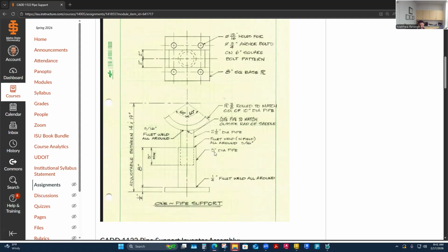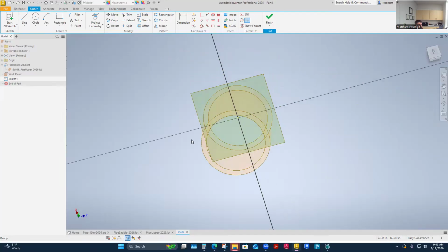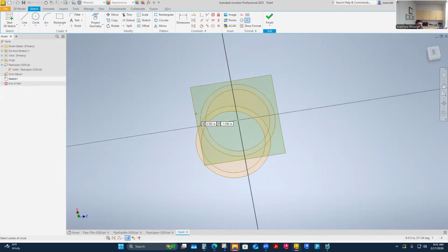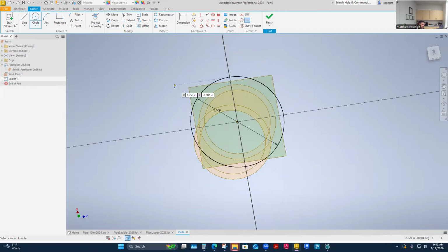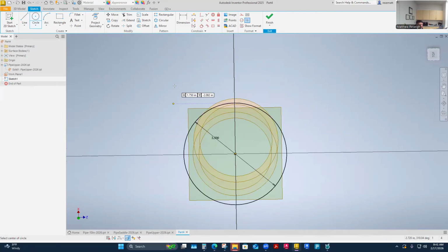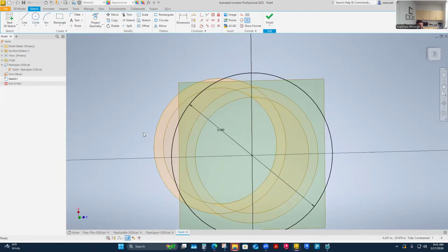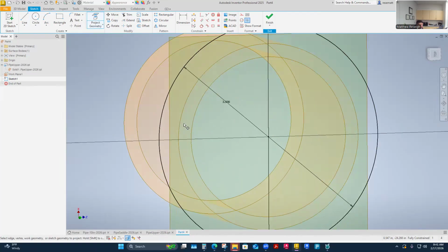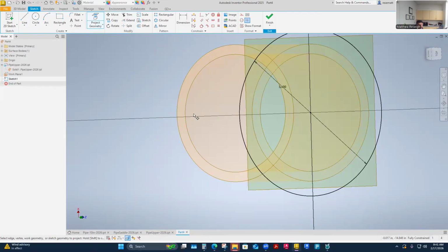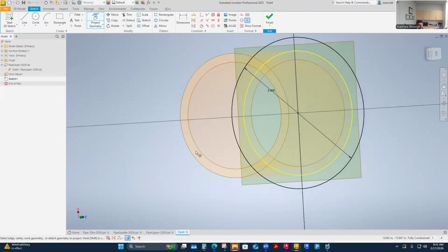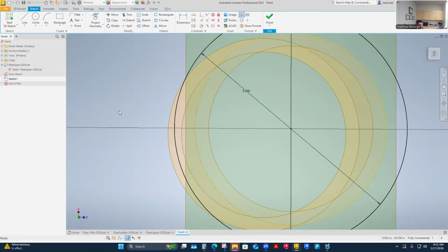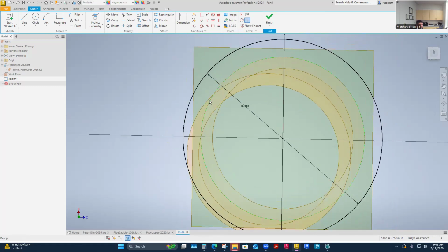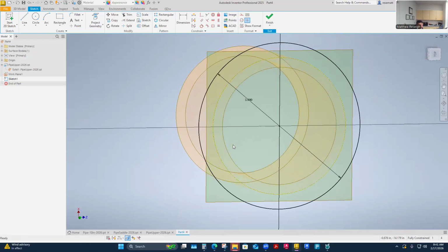And I'm just going to draw the diameters for this 3 inch pipe here with that offset. So I'm on that plane. I need a diameter here. So 3 inch pipe, I'm going to snap it to the center grid. It's going to be constrained at 3.5 inches on a 3 inch pipe OD. So that's how wide that is. I'll just choose schedule 40 here. Here's what I can keep track of: I can project in this geometry. This is the outside geometry. I may have to select something like this to project the outside diameter there. That's what's got to fit inside my part. And now I'm going to establish a wall thickness and make sure I don't jam into that or make sure it's not too much of a gap.